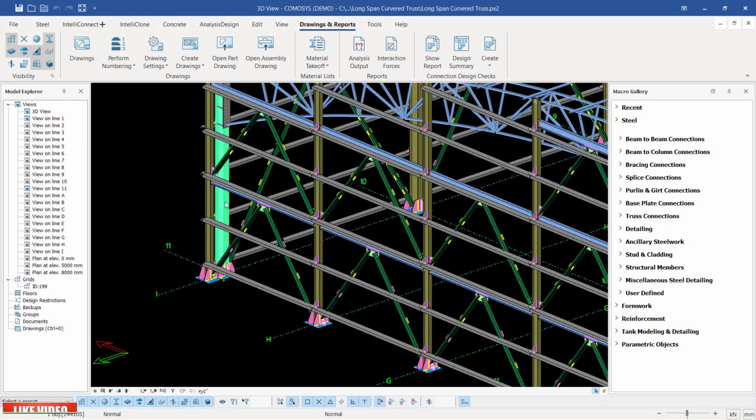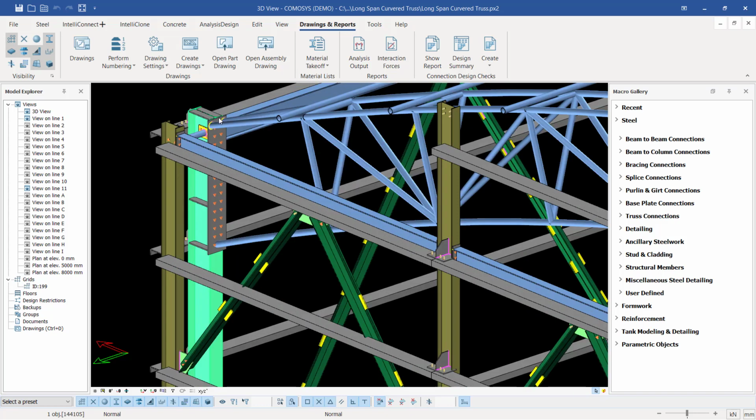Just note, prior to creating an assembly or GA drawing, first of all, make sure you've identified all the parts by numbering all the parts. If you fail to number them, you'll not be able to generate drawings, because sometimes it fails to generate. So just follow the workflow: identify all the parts, then create the drawings. So I've picked this column because this is the part I want to create assembly drawings from. I will generate assembly drawings for various parts so that you see how they look.